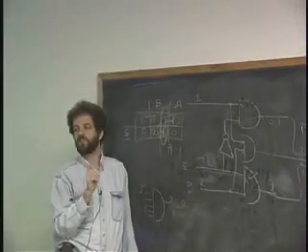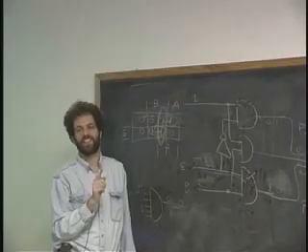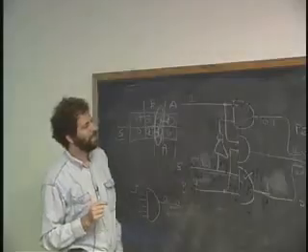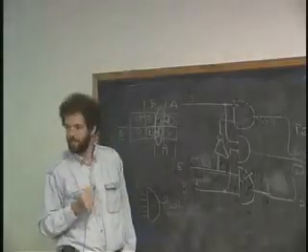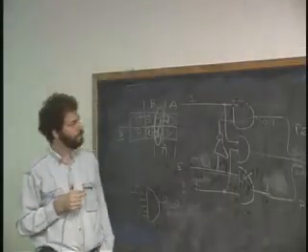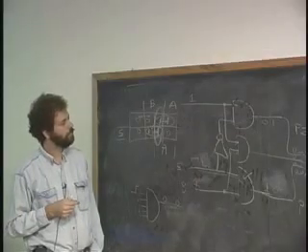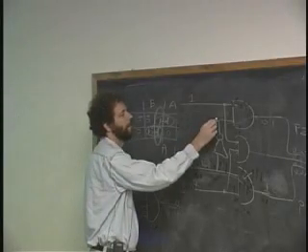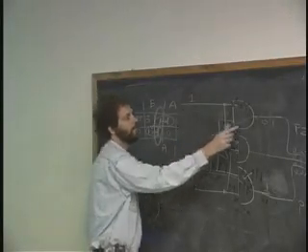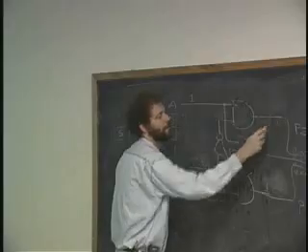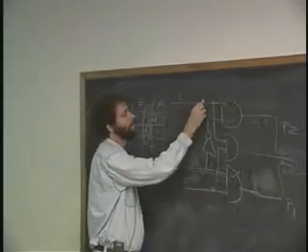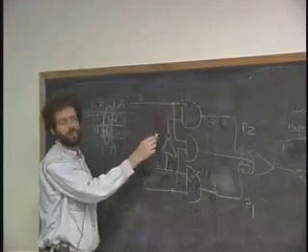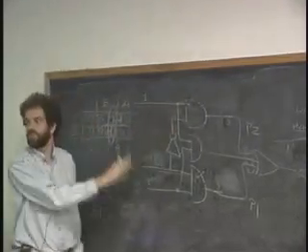Now, it's almost true. Okay? You see, I'm still getting that quizzical look, right? It doesn't occur when we're going up through the change in S gate. If this changes from a 0 to a 1, and it was 0 before and 0 after, which is what we're stipulating, then this must be a 0. And if this was a 0 throughout, then this thing can't glitch. And that's true throughout the whole circuit.